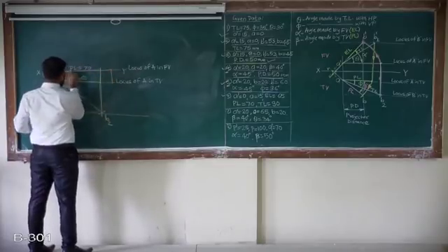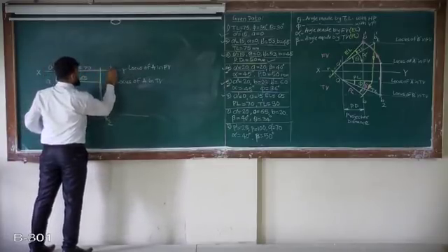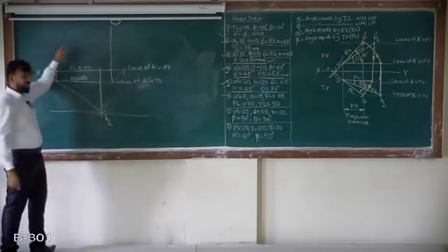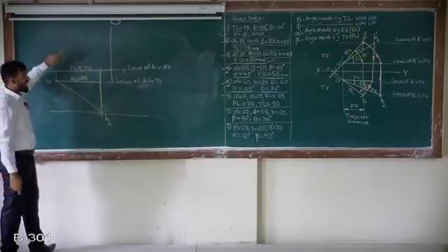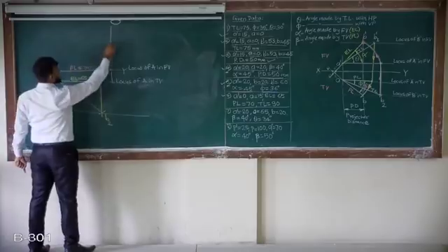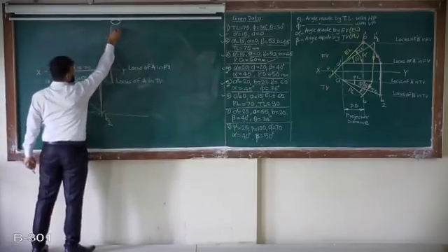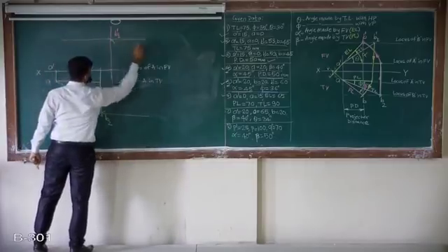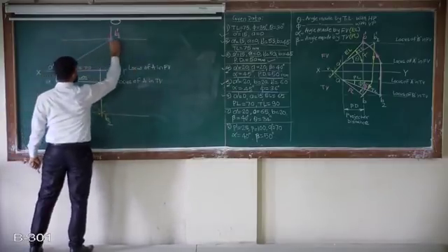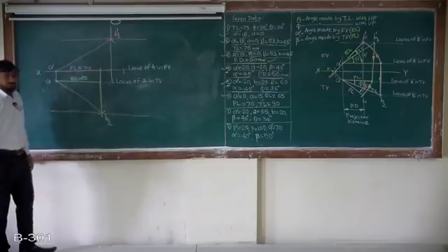This is plan length PL. So project this PL line in front view and from A dash mark the true length. This point is B1 dash. Draw the locus and join it. So that's the problem done.